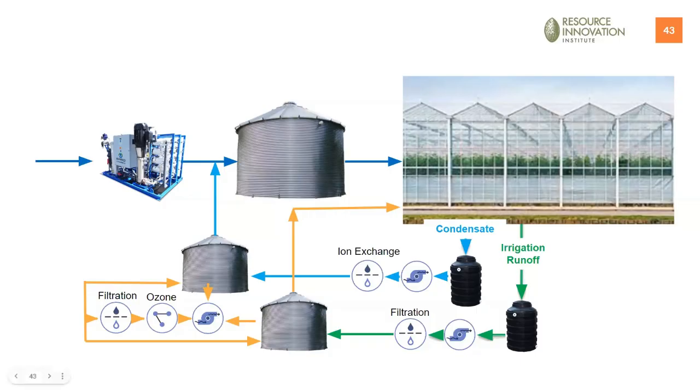And often you can design an ozone system, if those tanks are close to one another, that can take care of both tanks. It's important to note that the condensate, because it's relatively clean, is easier to treat with the lower level of ozone, and the dirty water storage tank usually requires a higher concentration of ozone to keep it disinfected.